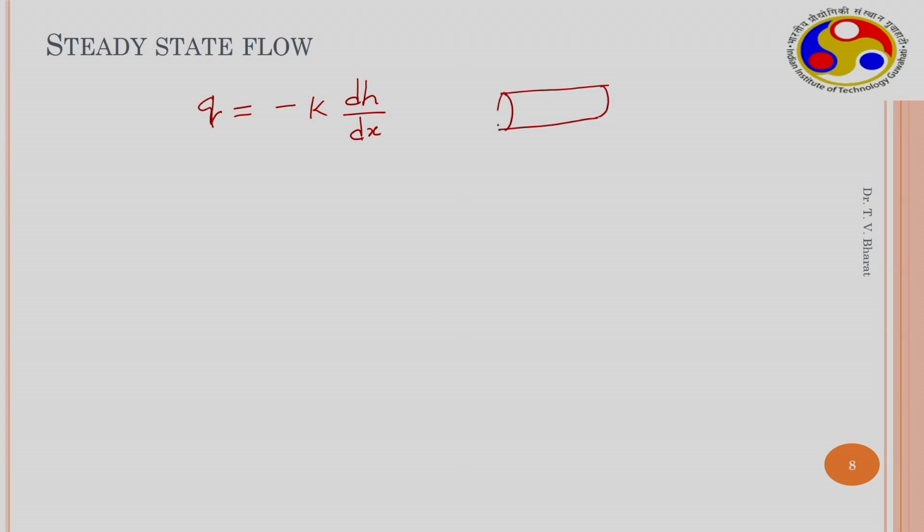If we consider a horizontal flow, the elevation head is 0, and the osmotic suction head can be included if that is present, but generally when the solutes are not present, this is also 0. So essentially the total head is because of the elevation head alone.